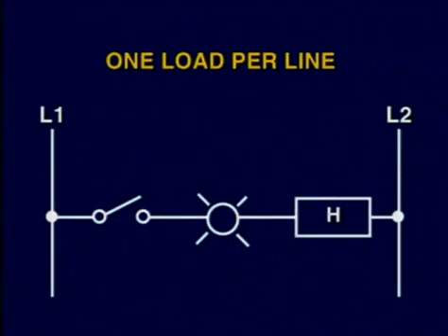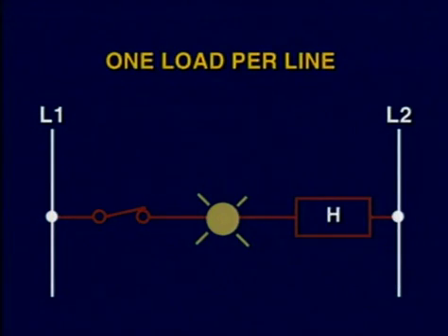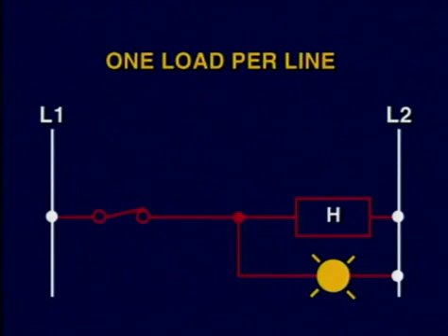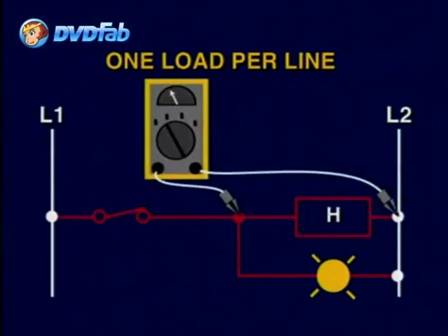In this wrong configuration, when the switch closes, neither of the two loads will receive the entire 120 volts, which are required for proper operation, and therefore will result in a fault. In the correct configuration, both loads get a full voltage between L1 and L2, which is required to properly operate. If we place a voltmeter across each of the loads, we would read 120 volts AC.